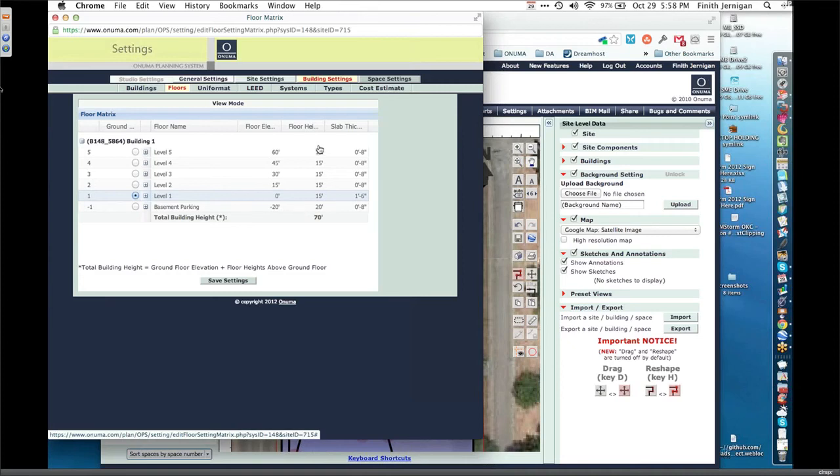So all of this the system took out of the Revit model, and the slabs that are there, we must have had a 1'6" first floor slab, but all the rest of the slabs were 8-inch slabs. These can actually be set here, and they'll change the model. I'm not going to go back out to the 3D right this second.